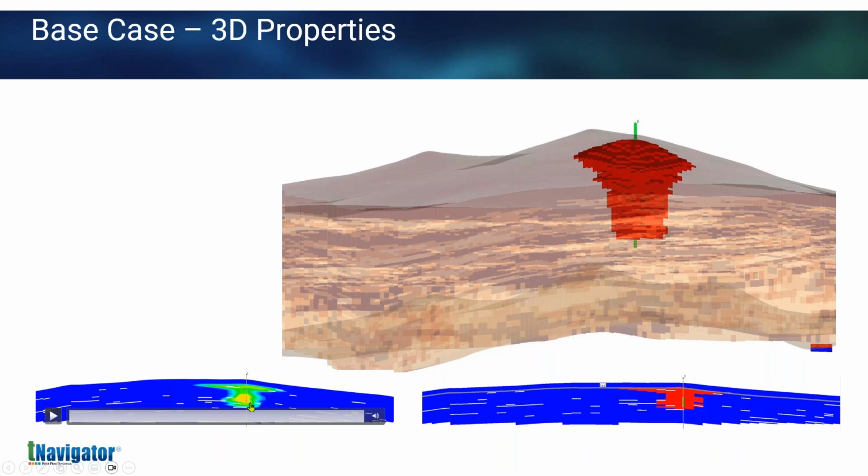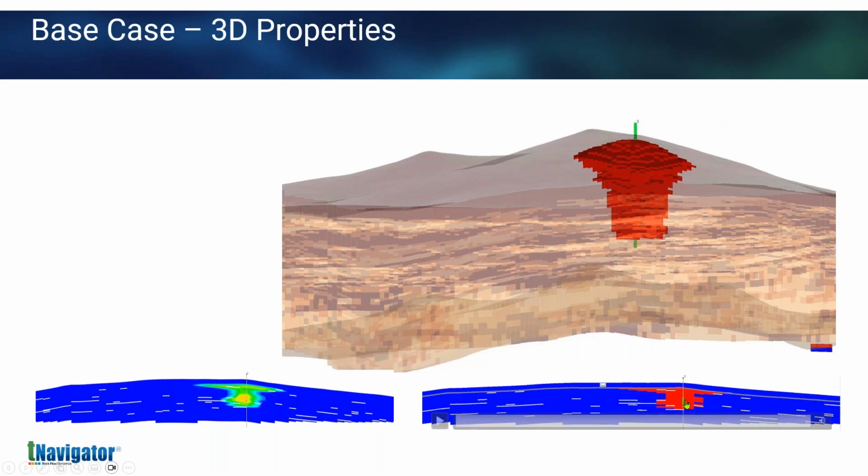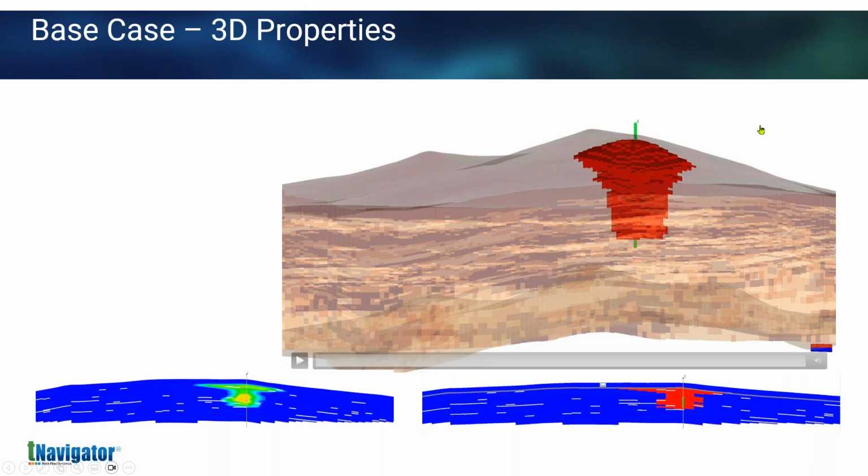And over here, we have the molar density of CO2. In this view, you can also see the extended grid. So this is due to the geomechanical properties that we've added. And I've adjusted the transparency a little bit so that you can actually see into the reservoir, which is what we want to look at, which is the plume. Additionally, you can see the perforation interval for this particular base case.